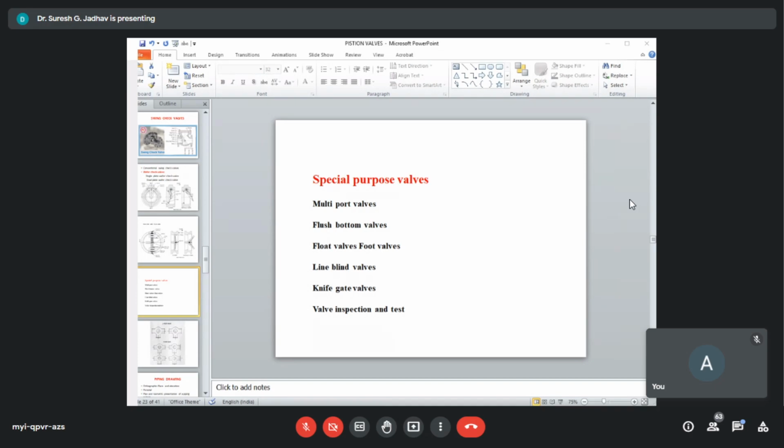In its simplest form, the sliding valve consists of two stationary steel plates with large holes drilled through them. A third plate slides between the stationary plates to perform valve operations. When open, this design offers no resistance to flow.